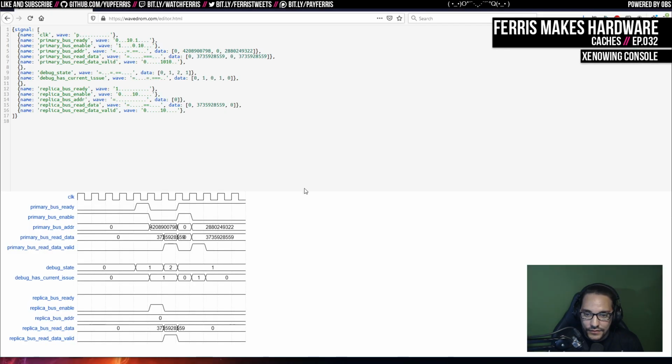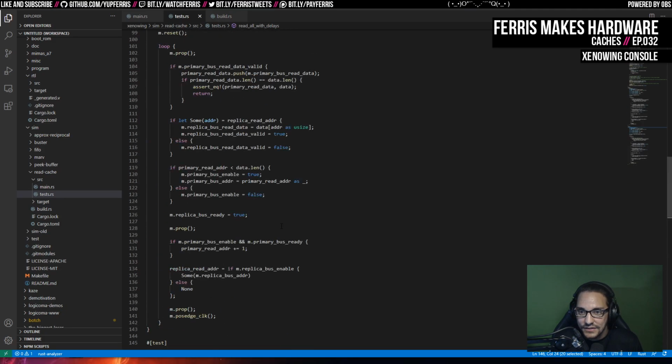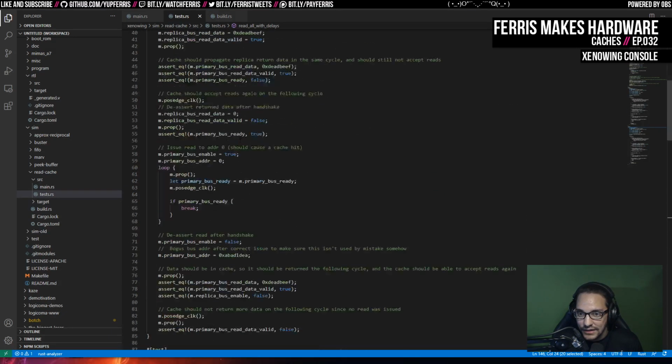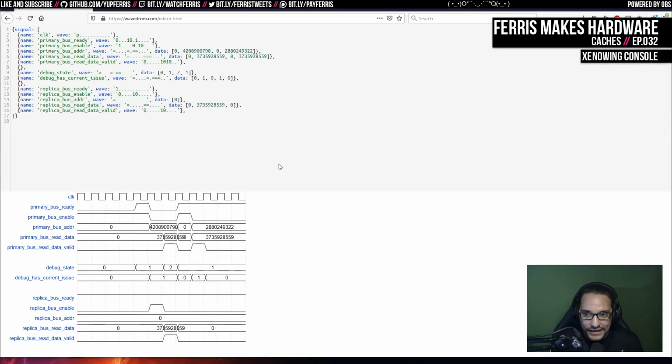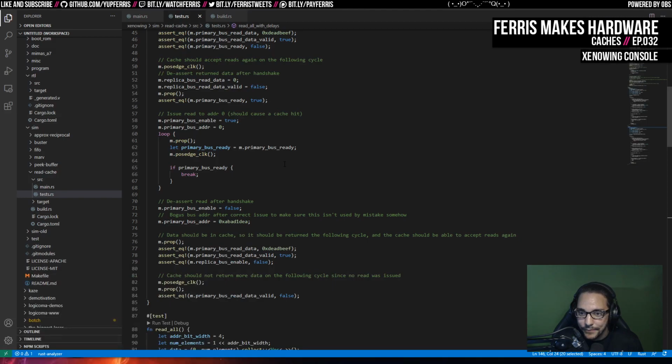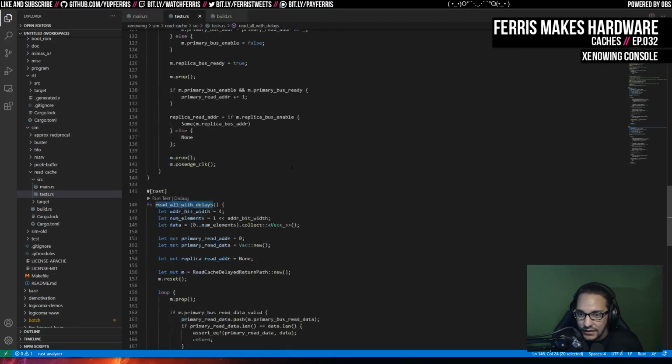So yeah, my point is I need to, at some point, implement this kind of trace stuff automatically so you can generate code to do this. And I probably wouldn't write it as this WaveDrom thing. I'd probably do a value change dump. Maybe I'll support both. I don't know. But I've just been lazy about doing that because I haven't had to do this kind of debugging with the system very often. Because most of the time when I'm writing these test bench kind of things, I don't really feel like I'm that blind, because I can see what all these signals are over time. But sometimes it really helps to see these together, especially when I had to debug this, because I think I had, again, this issue thing.